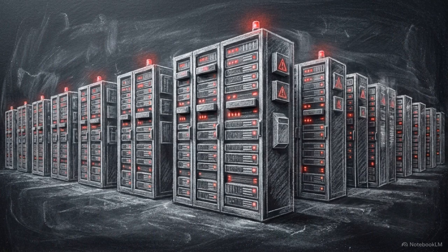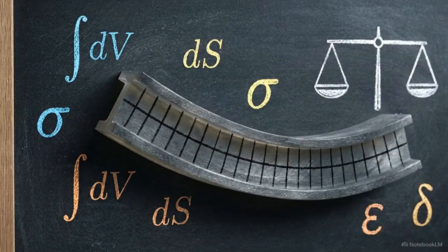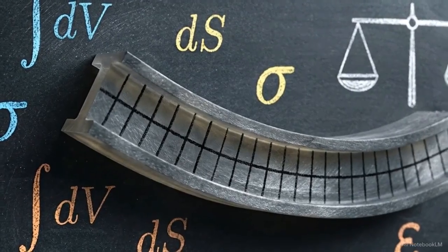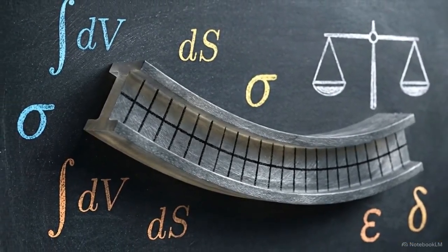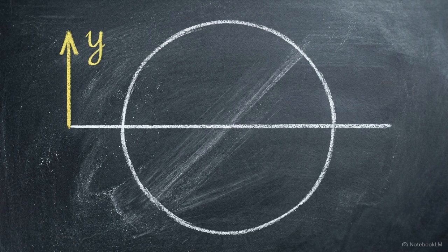However, calculating a true three-dimensional volumetric analysis for every element in a complex structure requires massive computational overhead. To reduce this complexity, we rely on Euler-Bernoulli beam theory. The core assumption is that cross-sections of the beam perfectly flat before bending remain flat and stay perpendicular to the neutral axis after bending. This geometric constraint allows us to map a complex 3D internal strain state directly onto a simple 1D curve. Under Euler-Bernoulli constraints, internal strain is strictly proportional to vertical distance from the neutral axis and the overall curvature of the beam.